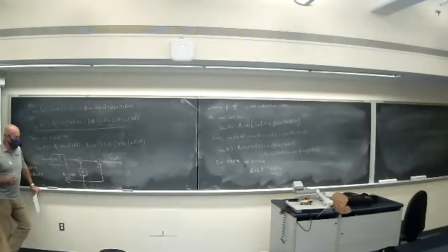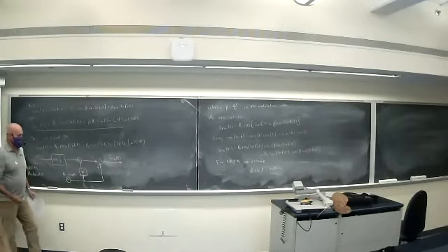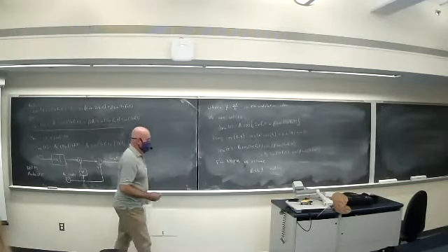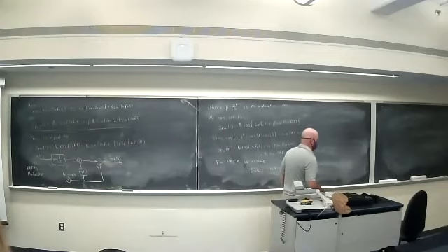So even though wideband FM is used more in practice, one way to generate wideband FM is to first generate narrowband FM and then do frequency multiplication, which we'll talk about. Frequency multiplication is not the same as mixing.